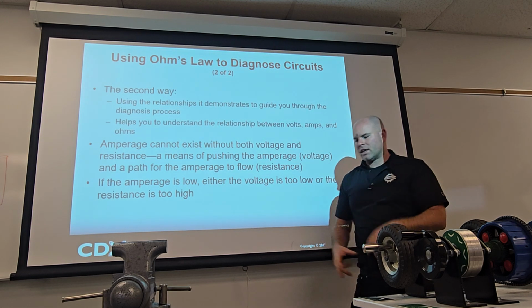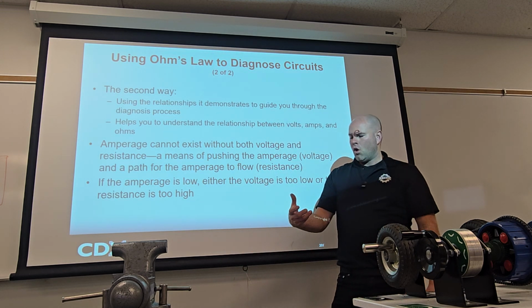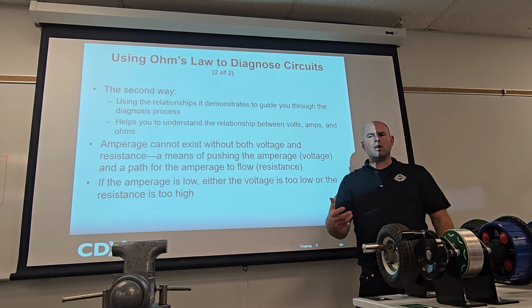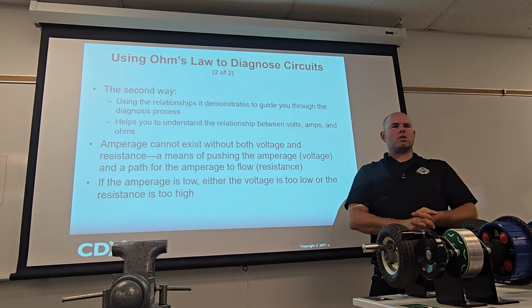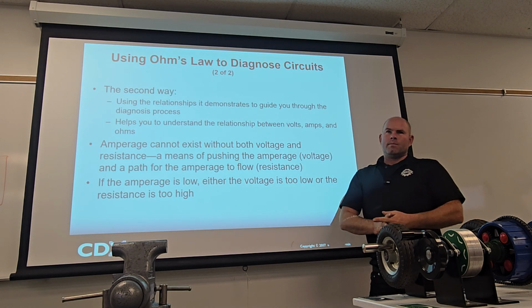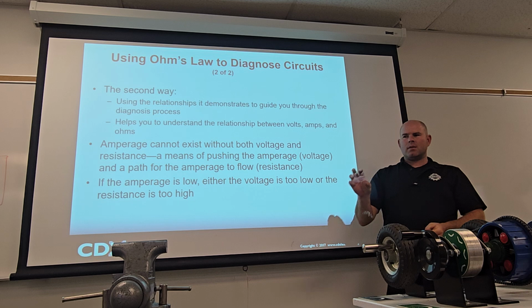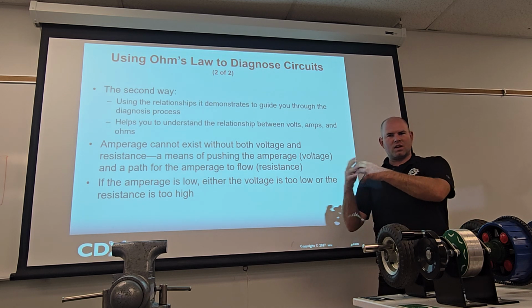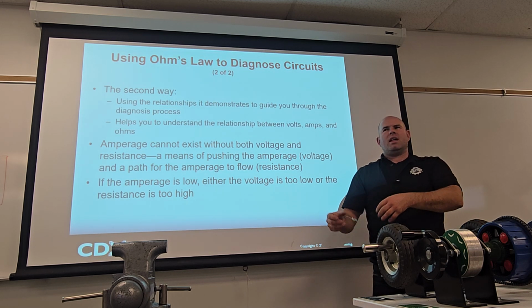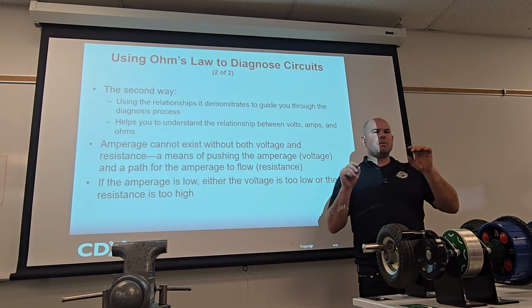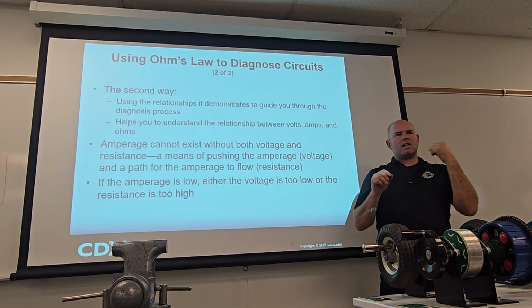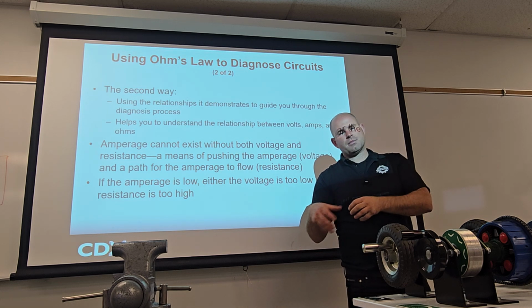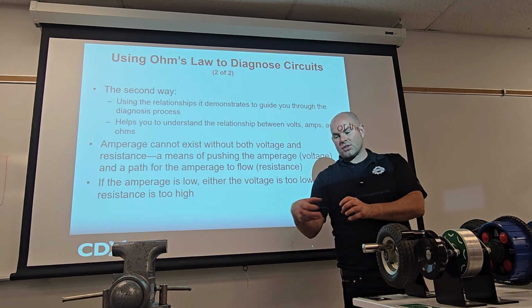And sure enough, one of my classmates pulls the connector out. He's like, oh, it's melted. And he's like, okay, yeah, we need to replace the connector. Right? So the way that my instructor way back in the day dealt with that was the bulb was dim. That means there's unwanted resistance in the circuit. Also, these bulbs were really bright and they were silver stars. And those tend to, for whatever reason, pull a little too many amps and they tend to melt the connector right there.